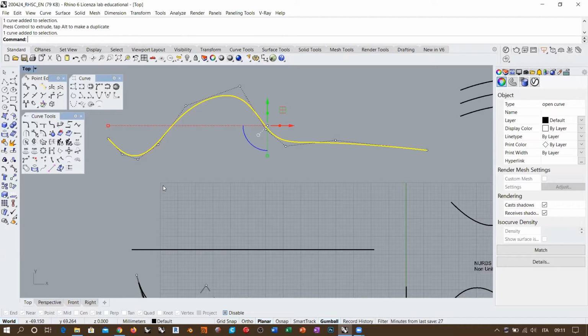So, for example, if we think about a normalized vector for a degree 3 curve, the first values should be 0, 0, 0, which is a full multiplicity knot with parameter set to 0, which is the starting point. And then in a normalized version, you should have 1, 2, 3, 4, x. I don't know how many control points we have in this hypothetical curve. And then the last one, which will be the last value, full multiplicity. This is a uniform knot vector with a constant step, constant separation between the knot values.